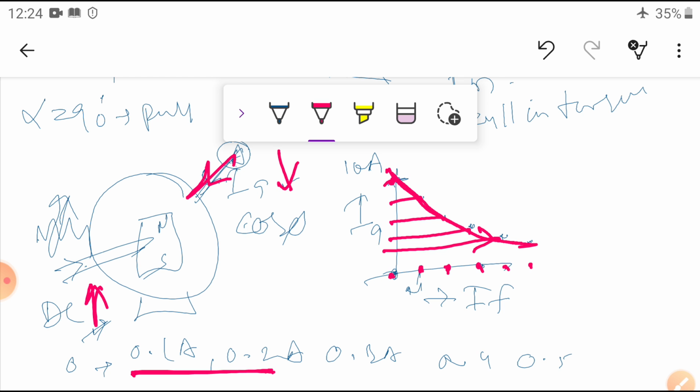Now we have some idea: if the field current increases, the current taken from the supply also decreases. That's why we get the minimum current bill from the NPDCL people. So I thought I would increase it further. Now I am greedy, I want to reduce the current further, so I increase the DC supply further, to 0.6.